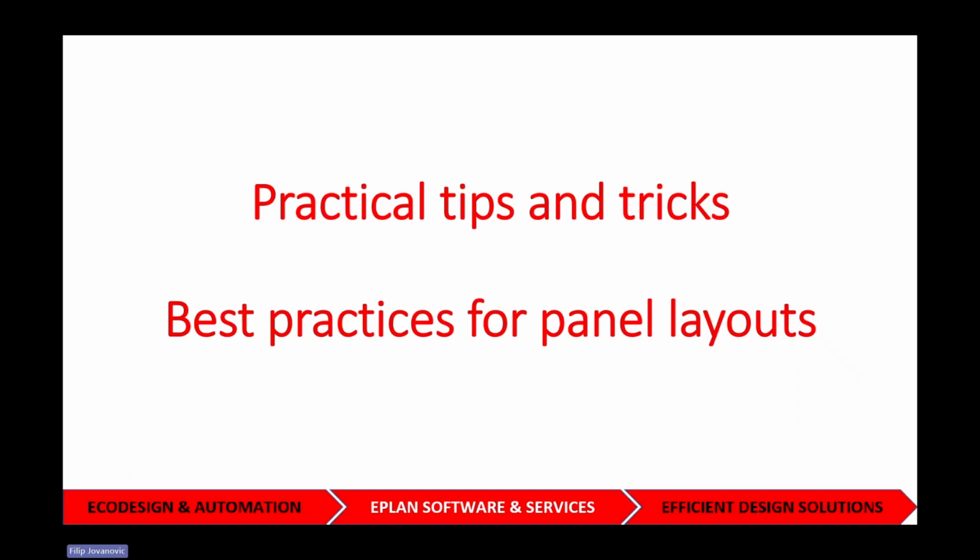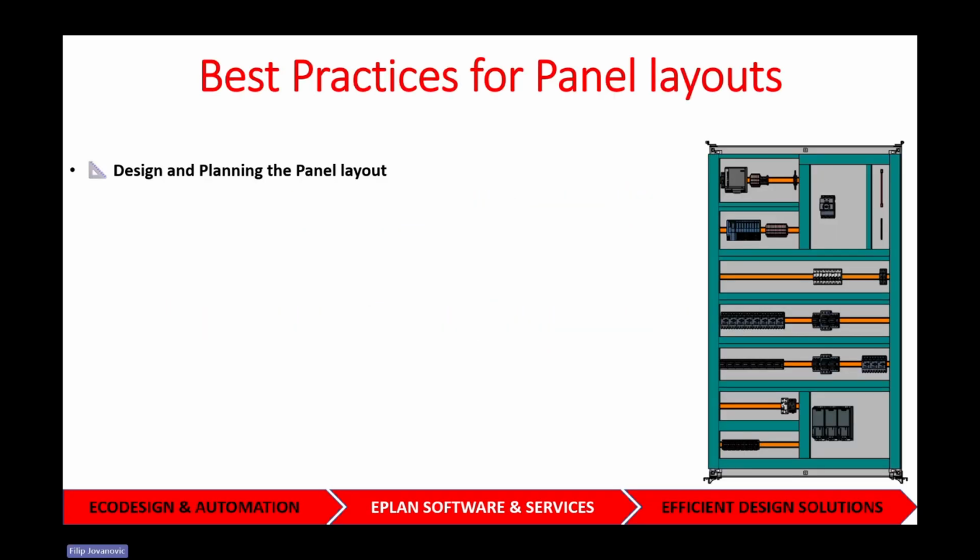So best practices. Before you even begin to do your panel layouts, whether it's 2D or 3D, you first have to have a schematic already drawn up in Eplan with all your parts, all wired properly and everything. Then you can begin to plan it out.